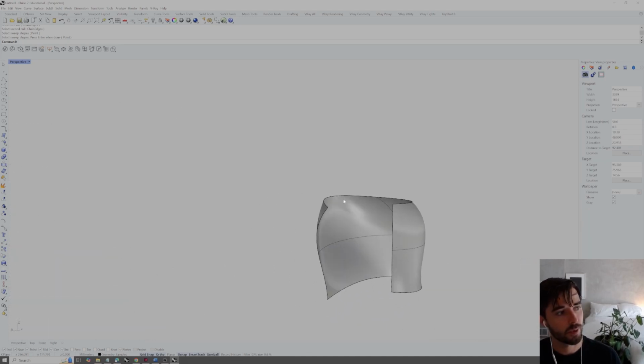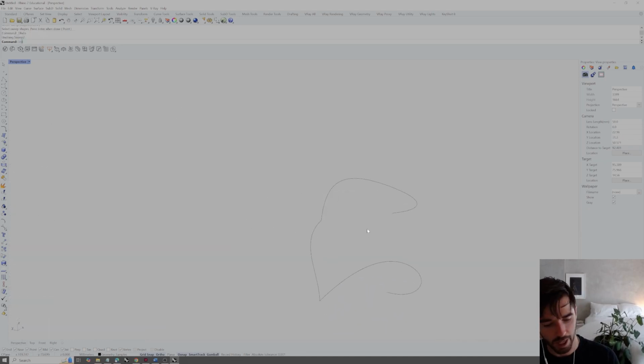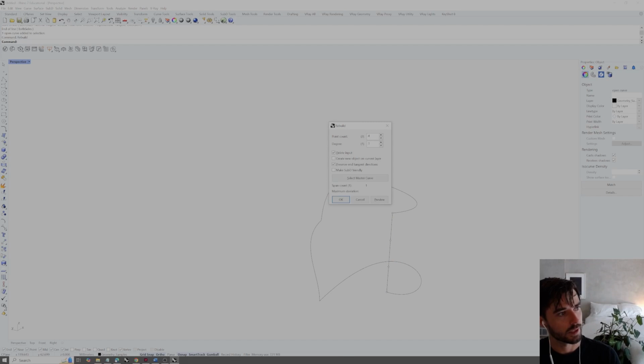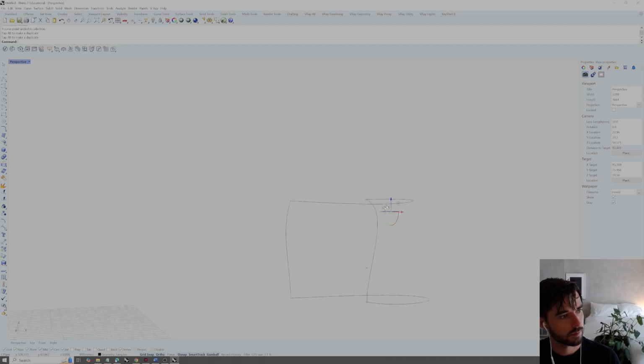that geometry. If we wanted that profile to change as it goes across those 2 rails, we can draw another line here at the end, rebuild this, select the control points, again type sweep 2, select the rail at the top, the rail at the bottom, and now it's going to prompt us for our sweep shapes. We want the profile at the beginning and the profile at the end.